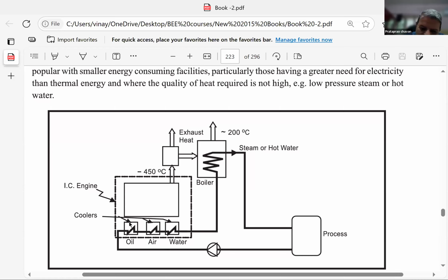The high temperature of the oil, we want that it should be reduced. If we absorb that same heat in this water, then the temperature of the water already going to the boiler will be raised by at least 10 degrees, 15 degrees. That much flue gas heat is less required for converting to steam. You got the point. The efficiencies are to be improved.